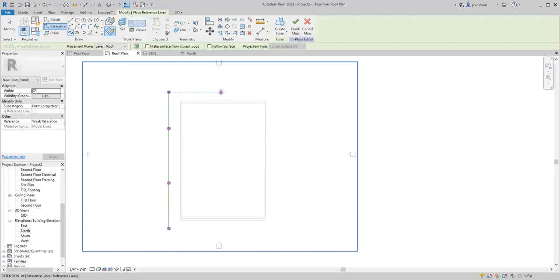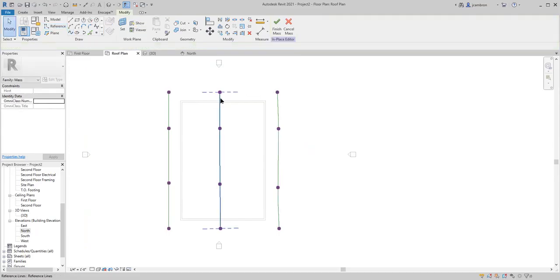And then I'm going to come up here and start again. What I'm trying to do here is just kind of line them up to the other points from the other spline. And I'm going to do another one just like that. Okay. So now I have my 3. I'll hit the escape key twice to get out of the spline tool. Now I have my 3 reference points.